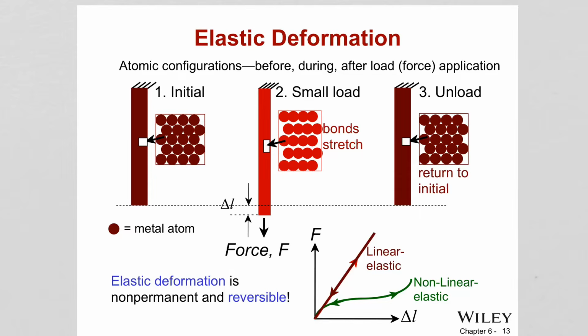So this tells you again where the elastic Young's modulus originates. It originates from atomic strength: how atoms are displaced by application of loads, and if we remove the load, what happens? You can see that initially, in number 1, the atoms are well packed, and in number 2 we apply the tensile force, trying to stretch the material. Therefore, you are stretching the bonds.